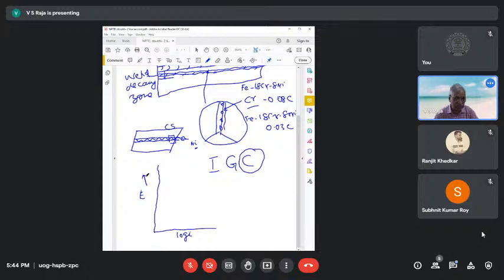This is towards positive direction of potentials. This is towards a relatively negative direction of the potentials, right? Suppose I look at the polarization curve of a stainless steel, it may be something like that. I'm just drawing a sketch like this. Okay. Now, assume that in sulfuric acid, this is the anodic reaction for the stainless steel. And if there is a cathodic reaction, assume that the cathodic reaction cuts somewhere here.